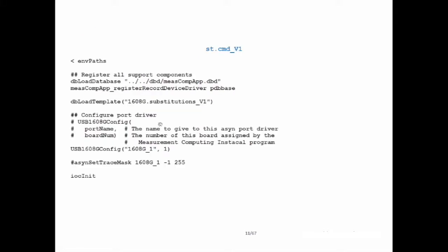This is so that you could have it put out an analog pulse instead of just an analog value. So there's a binary output record here that says, is it a normal output, meaning just a level, or is it a pulse? And if it's a pulse, this is the record that makes it go back to the return value when it's done. And we've got a couple more records here that we stuck in to be able to tweak the value. So we've got a tweak up and a tweak down, so the user can click and make the voltage go up or down.